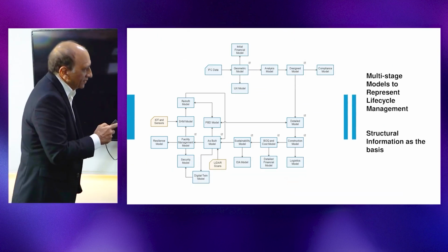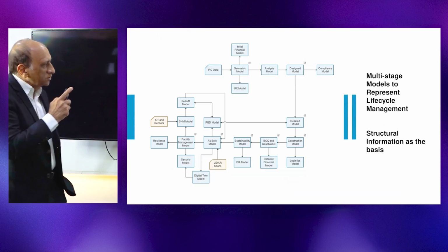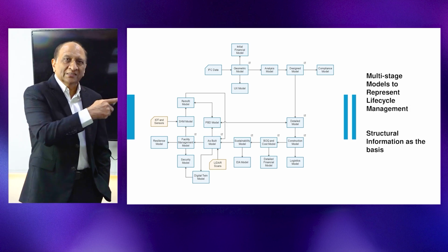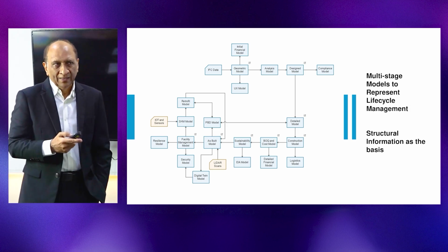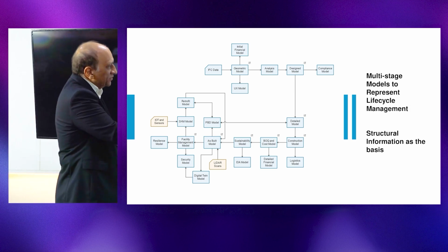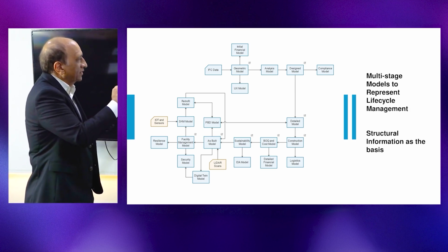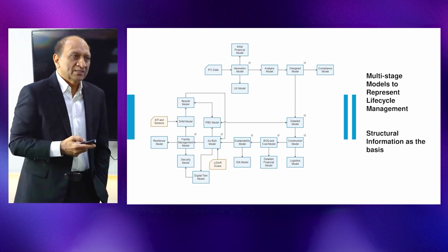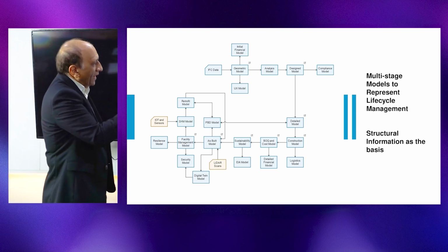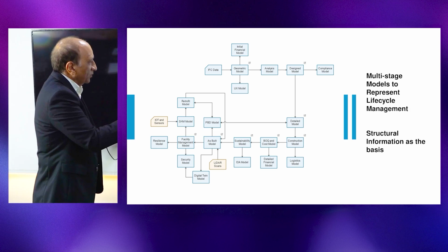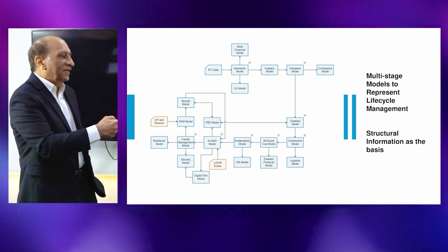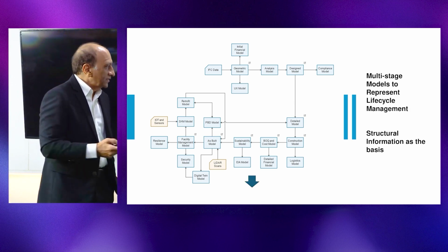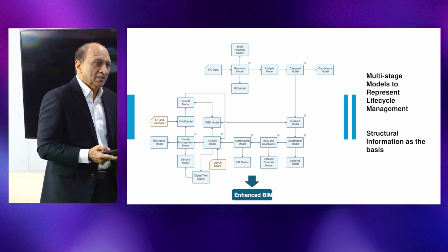This is an expanded model for lifecycle management. It goes much beyond what I presented earlier, and it is mostly from the structural engineer's point of view. And so it starts with IFC data, for example. We have a starting model, post-analysis structural analysis model, design model, and then compliance model with the code, so we can have the permits issued. Then we can go to the detail model, and then we can have the construction model, BOQ and cost model, sustainability model, logistics model for bringing the material in, detailed financial modeling for the final costing, and the EIA model for the environmental studies. Then go to the as-built model after the construction is complete.